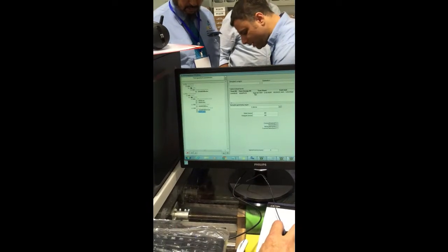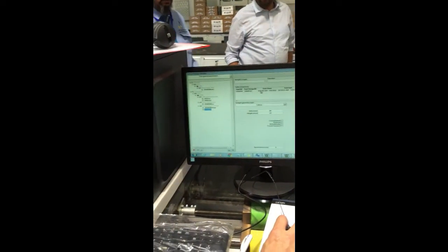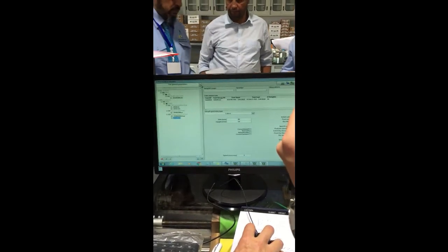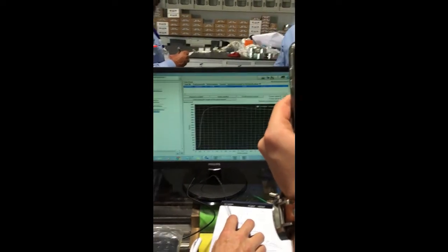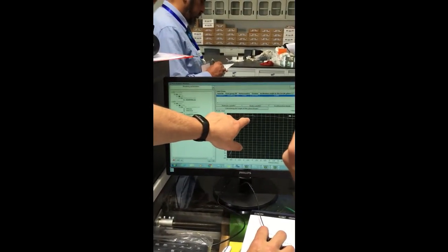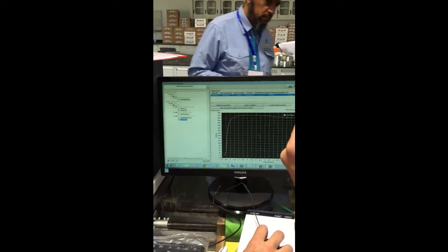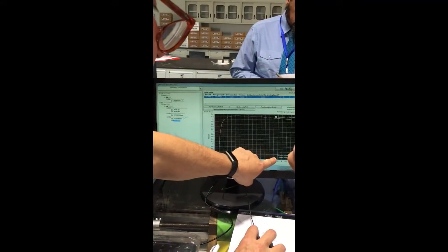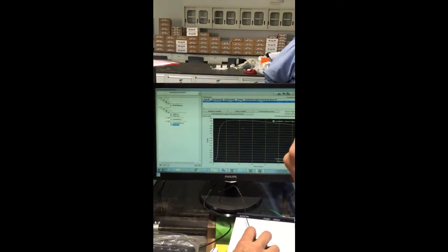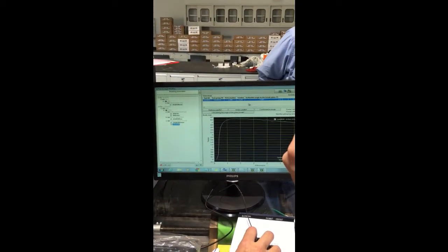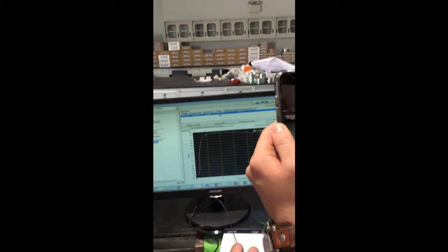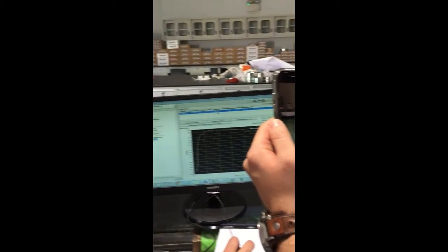And we see that it started about 9:57, finished this moment, took 44 samples. And you just see the breaking parameters, you see the curves. And you see that I told you more or less this point was the breaking. Unit is kilopascal. I can put, for example, kilograms and millimeters. And I see that breaking was at 1.6 millimeters. We talk about 1.5, 3.2 kilograms.